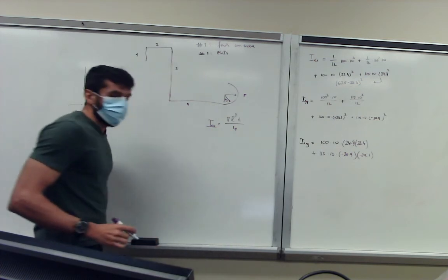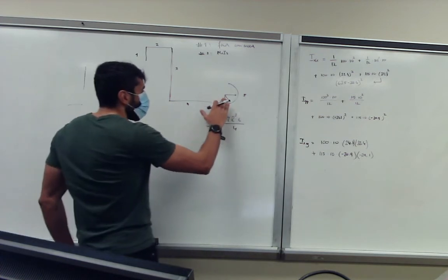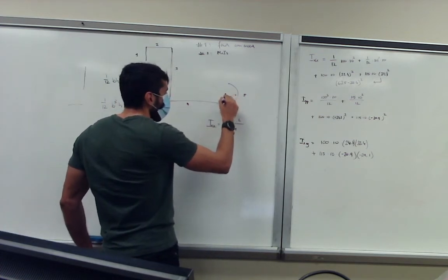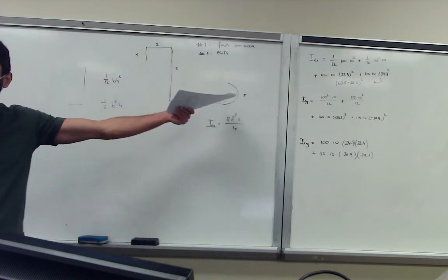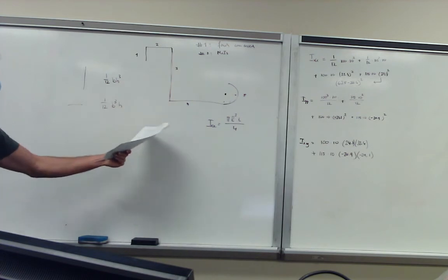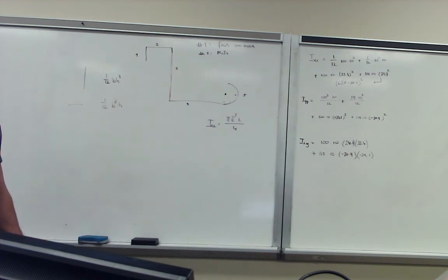If we get different geometries, we just look up the moment of inertia for those geometries. So you come up with the different components, and this will be with respect to a centroidal axis, say, or the centroid that will be laying there. Now you have to add the Steiner term for that axis coordinate system transformation.